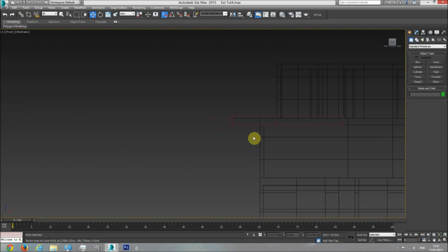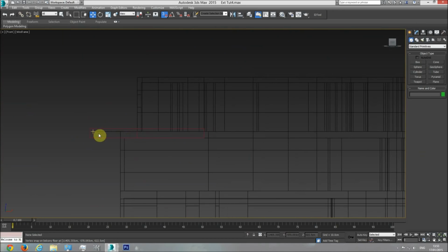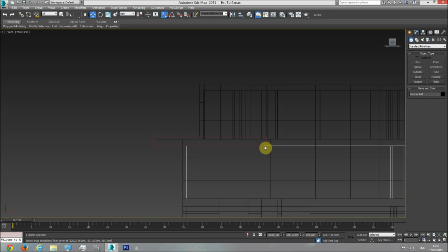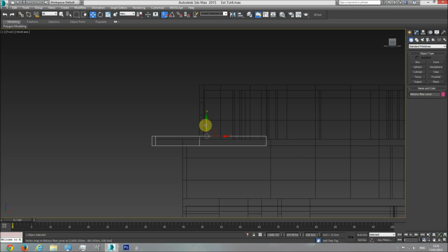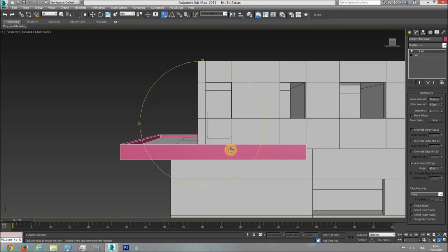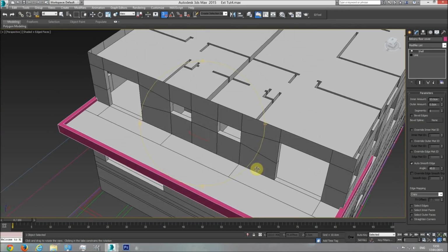Alright, so the ceiling of the first floor, this line here, represents the beginning of the cover. So the cover is aligned correctly on the y-axis, and the height of the cover is 53 centimeters. So everything is fine here. Let's just check that everything aligns correctly.